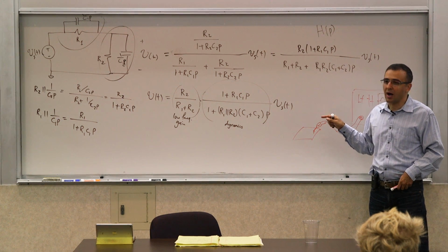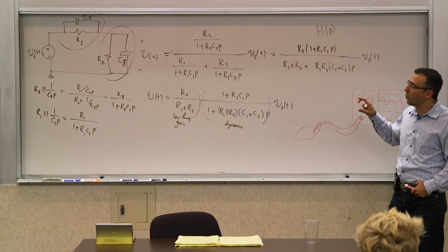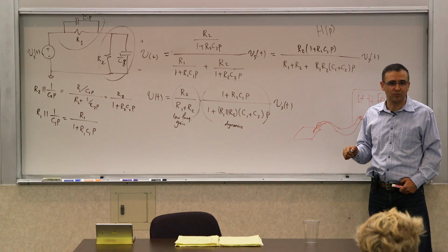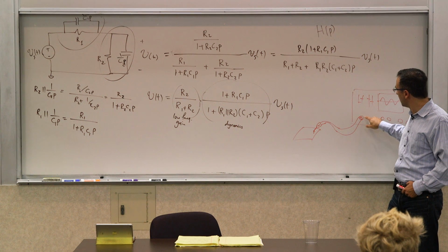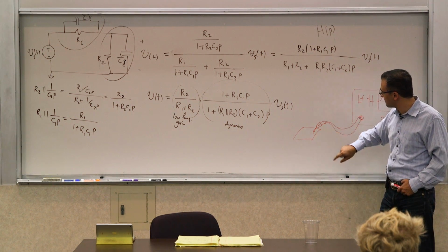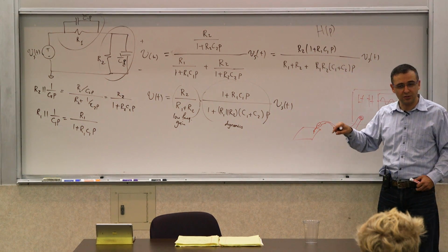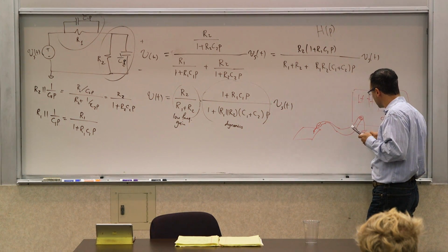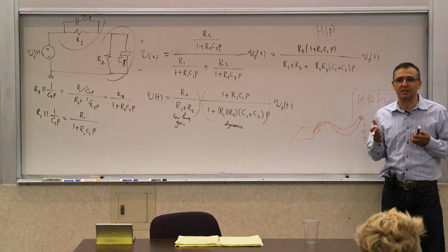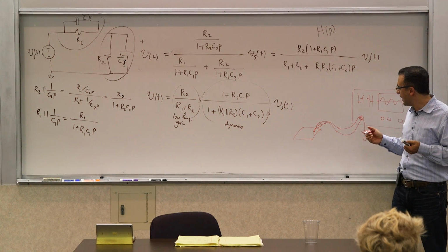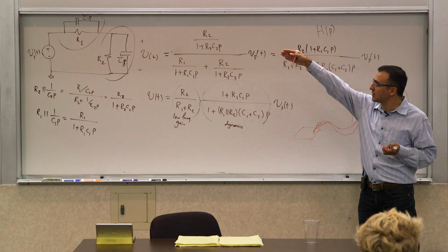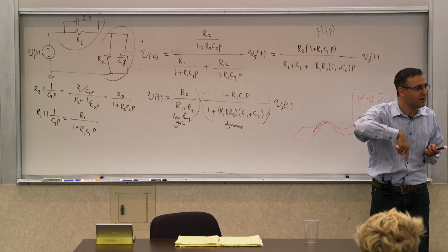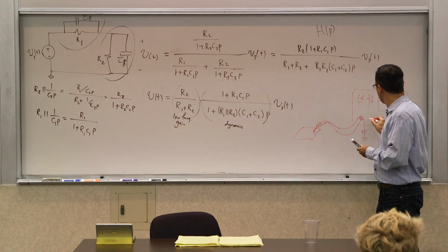You're trying to minimize the impact of what your oscilloscope does to your circuit. So you want the voltage that the oscilloscope sees to be a good replica of this. But this probe and this oscilloscope and everything, the oscilloscope input has some capacitance, right? So it has some input capacitance. You can't make something that has no capacitance. Now, if you just hook up this capacitance there, it will start degrading the signal, because if you're looking at something high frequency, it will just bypass it and filter it and reduce the signal. So it also has a resistor.